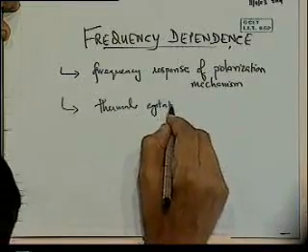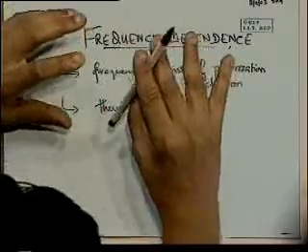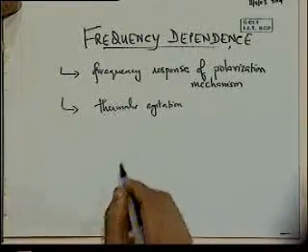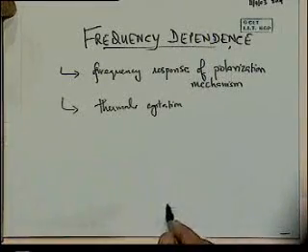Every time the field flips and the particular dipole wants to orient itself in the direction of that field, it goes on doing that. At the same time there is also thermal energy being given to the system at any given temperature that is seeking to randomize it and interferes with this flipping back and forth. So you're going to get losses. And it is these two things that are responsible for the different mechanisms being effective at different frequencies.